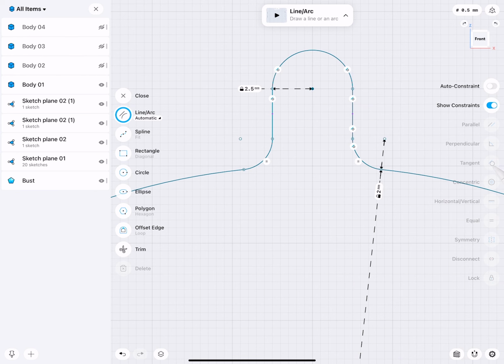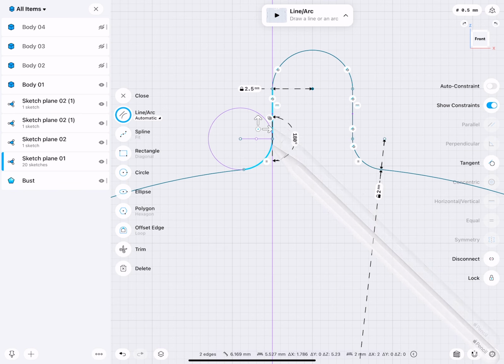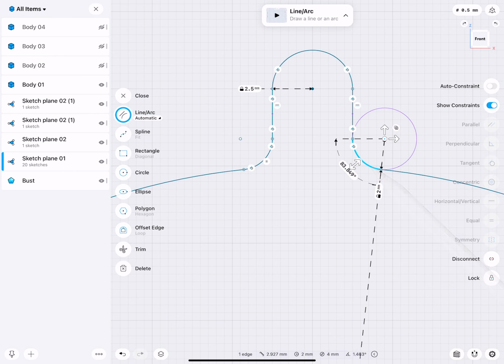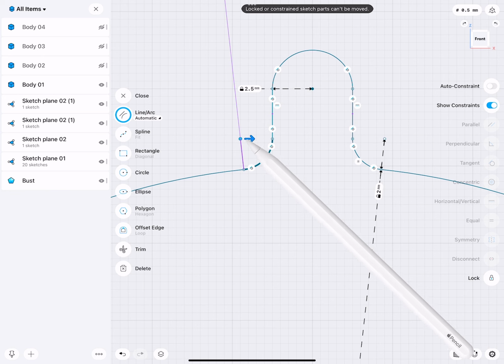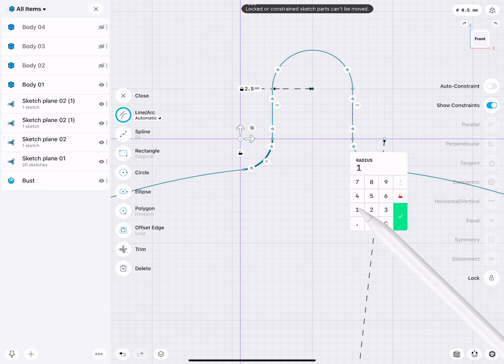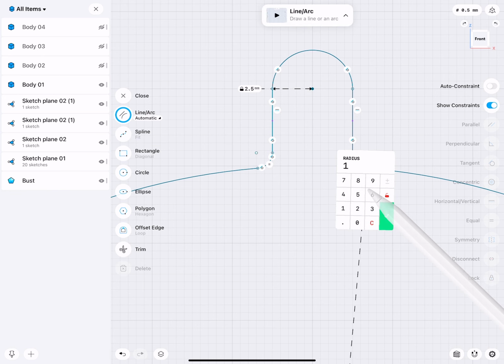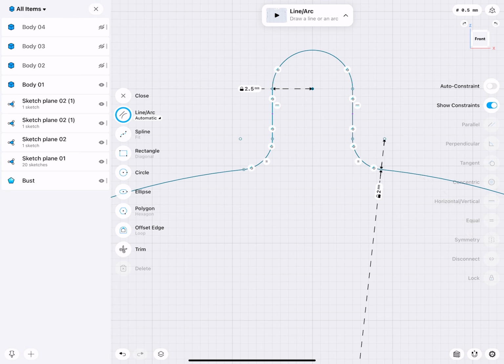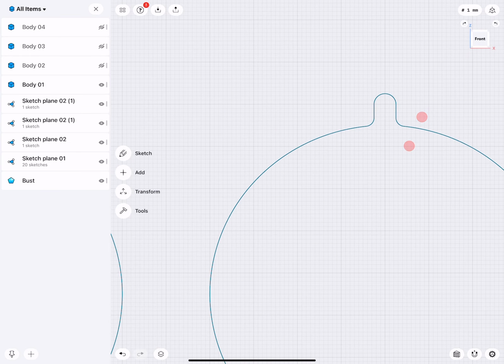And a tangency and horizontal, vertical. Okay. And then this is equal. Yeah, tangency. And tangency. Again, because this is a sketch solver that tries to solve basically what I want when I modify it. You see now it doesn't do it anymore. So I need to give it rules and a structure. And I created a structure, and now I can explore everything the way I want.